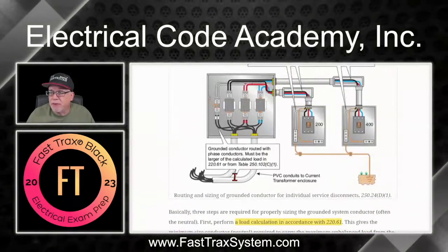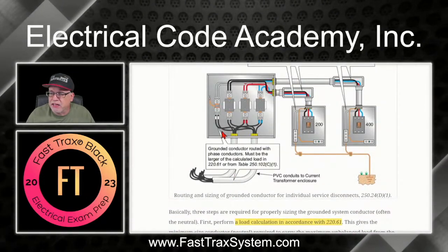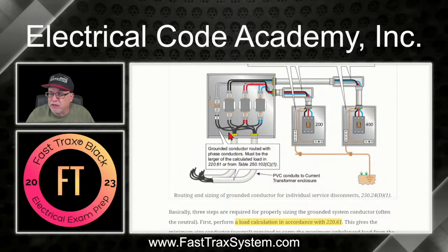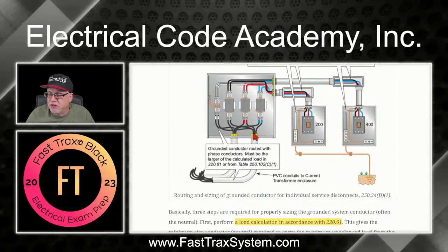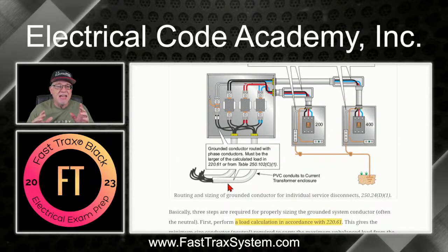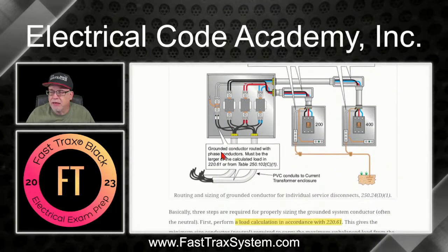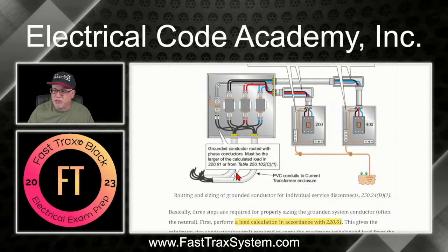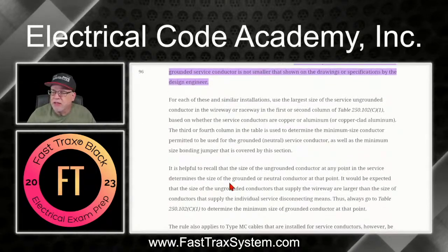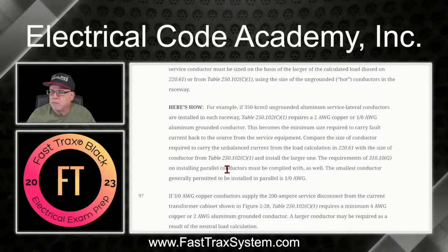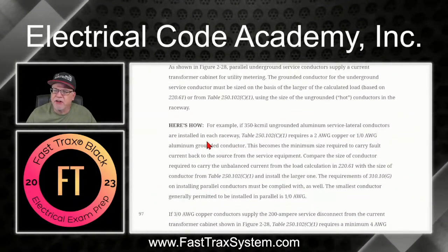So again, just to point back here, okay, this grounded conductor is based on the conductors in this raceway, this conductor size in this raceway, okay, be careful how you size this grounded conductor. Okay? Essentially the same as we're doing down here. All right, but I just want you to be aware that we're still following essentially the same rules. Nothing's changing.